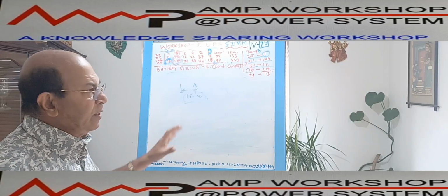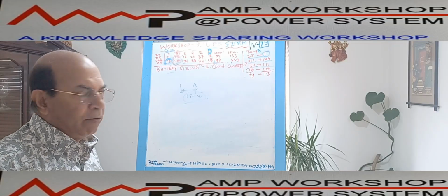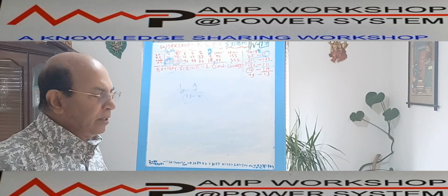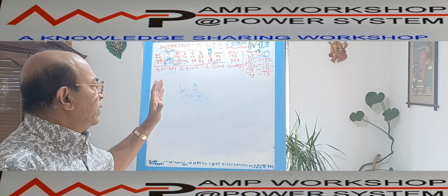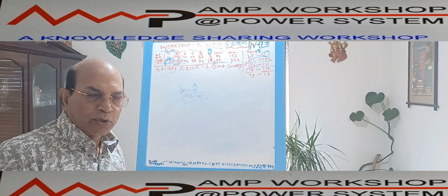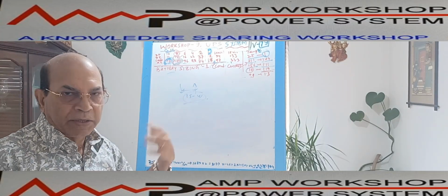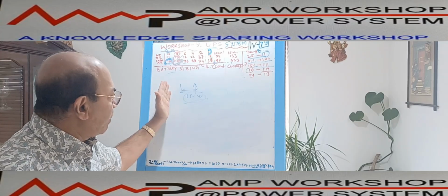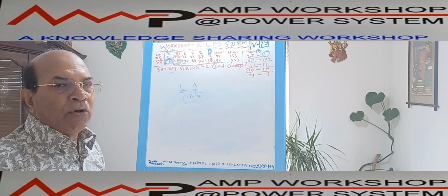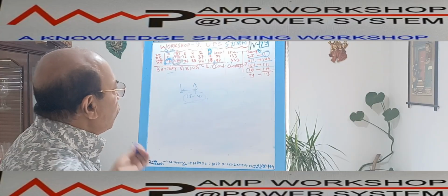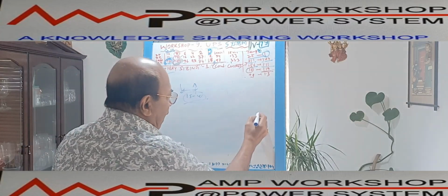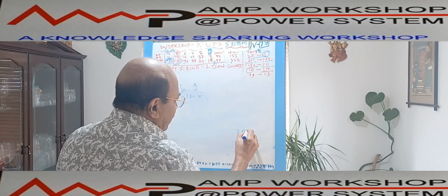So let us consider at this moment it is a gas turbine plant, while the diesel generator is the emergency generator. Once the gas turbine drops, the emergency diesel generator should start up. If the emergency diesel generator fails to start, then within 2 hours, hopefully either the normal power supply or the emergency generator will come into the picture. So we will consider the UPS has to cater power for 2 hours. We are considering it that way.